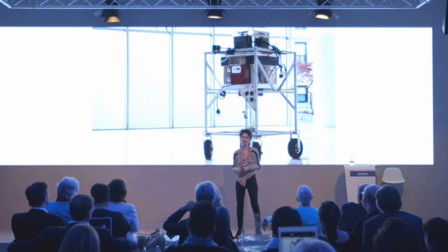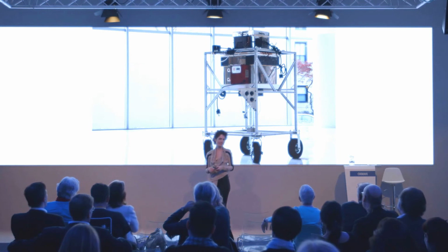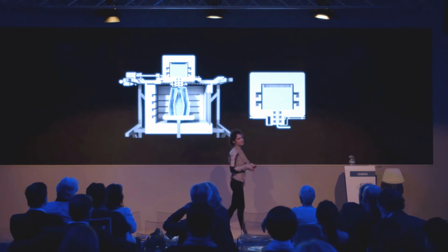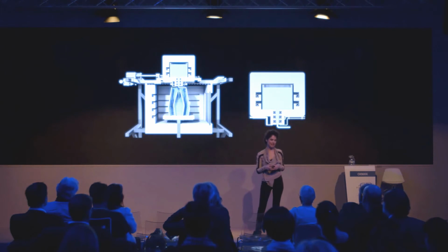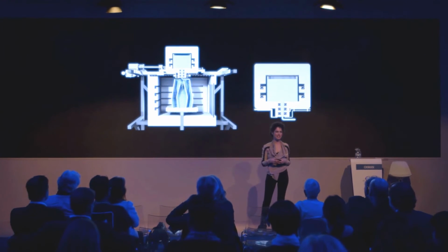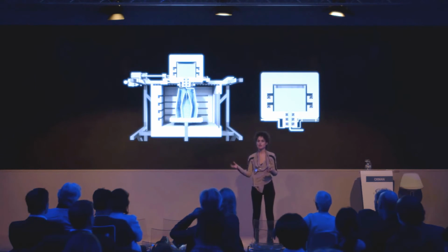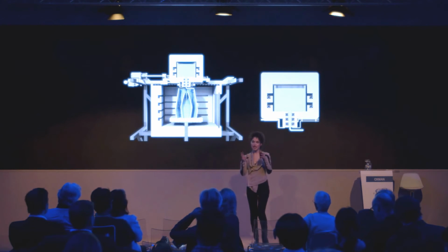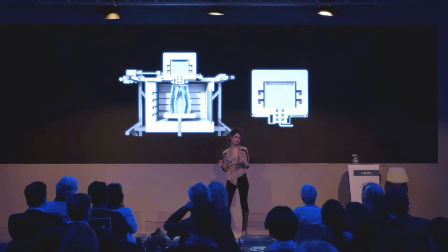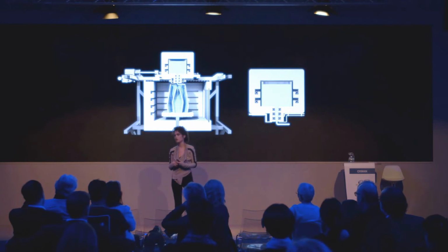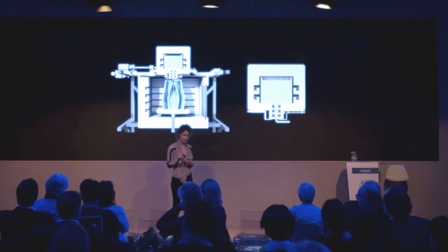This was the printer that was designed and architected from scratch in my lab. It was a collaboration between Mediated Matter, the Glass Lab at MIT, and the Mechanical Engineering Department at MIT. Before I show the video, this is how the printer is designed. It has a kiln cartridge that allows us to take in molten glass and control the gradient of temperature, thereby controlling the viscosity of the glass, thereby controlling the geometry of the deposition.